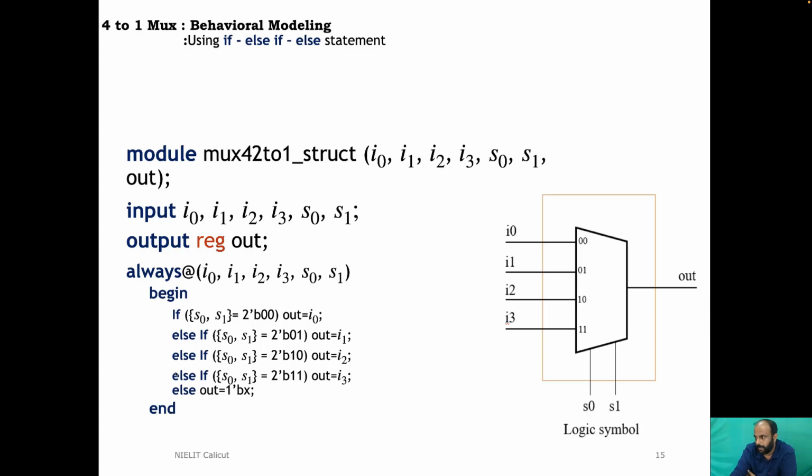So it is not a must that we write begin and end. Begin and end are used for combining multiple events that happen sequentially. But it doesn't hurt to give that out as well. If you would like to give it a more structured view, you can always add a begin and end. It just serves the purpose of opening braces and closing braces. Anything which happens within begin and end happens sequentially. So that completes it. So you can write endmodule.